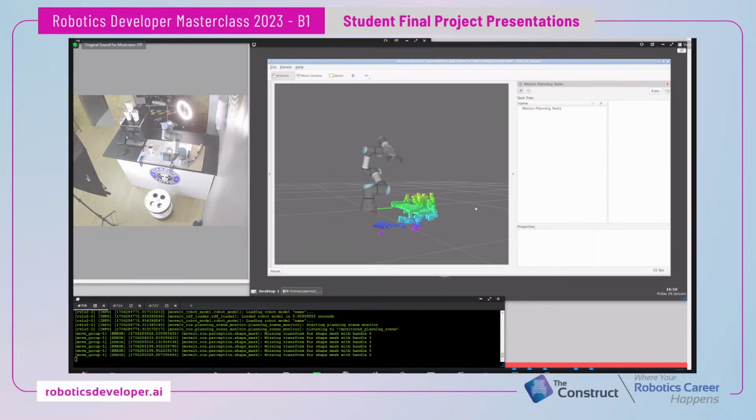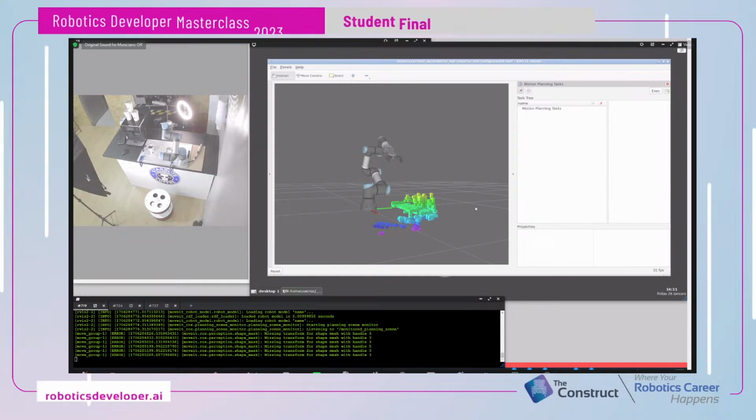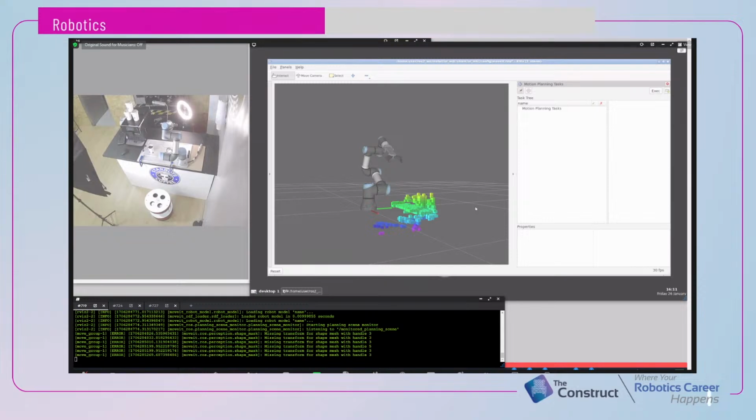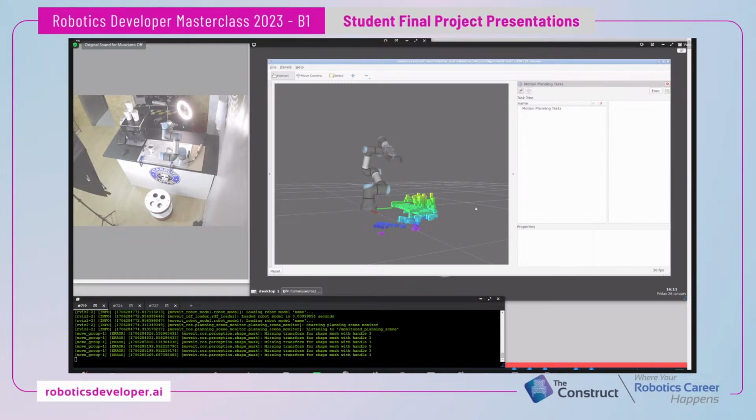One issue that I was unable to pinpoint the source of, I suspect it's a little bit of Point Cloud Library, a little bit of MoveIt, is that when the cup is detected and the perception data is passed to create the object, it would randomly assign the z-axis of the object to be up or down, which in the broad scope of things doesn't matter too much.